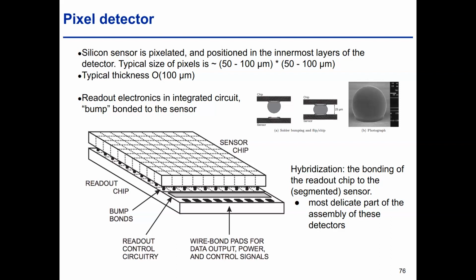And you see the space between your junction and your readout chip is of the order of a couple of tens of microns. And in fact, a lot of the reliability in producing them is how many of these connections are breaking, what happens if I have thermal stress and there is some mismatch in the material between the two different elements, and then they will contract and expand a little bit differently. That will put stress into these bonds and they can break. So there is a lot of work that goes into managing these types of stresses and making sure the design is such that this connection stays stable for the duration of the experiment.